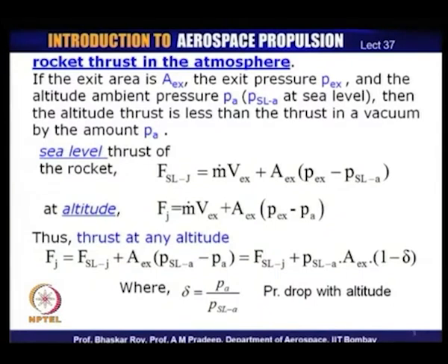We have seen, and we shall see more and more, that the flow is often quite near the maximum value most of the time. However, the value of V_ex would depend on the exit pressure, and if the exit pressure is changing, the pressure ratio across the nozzle is changing, and then the value of V_ex would continuously change also.